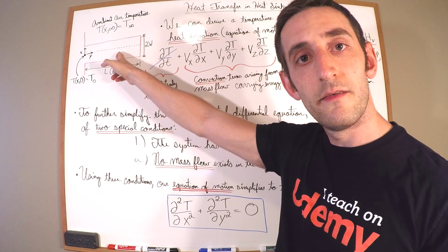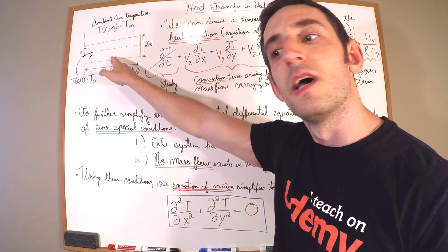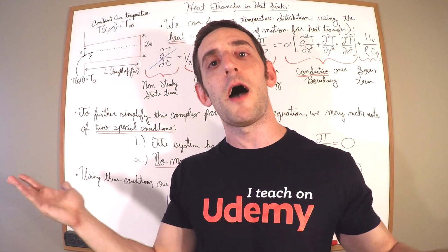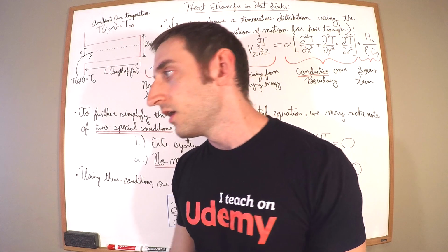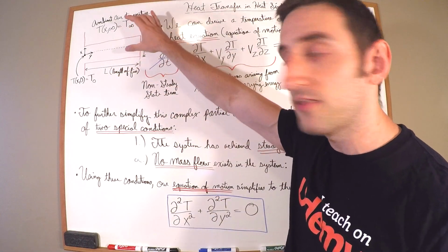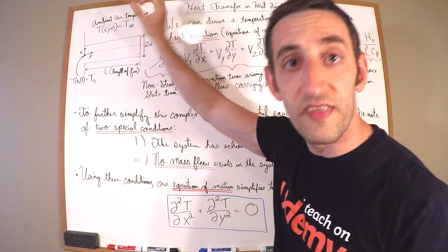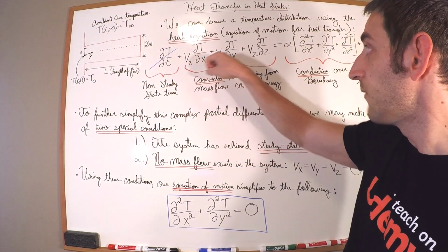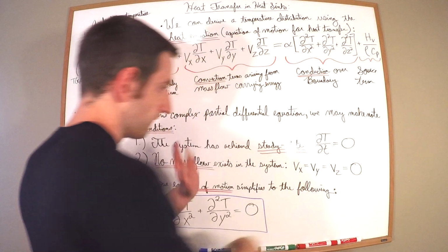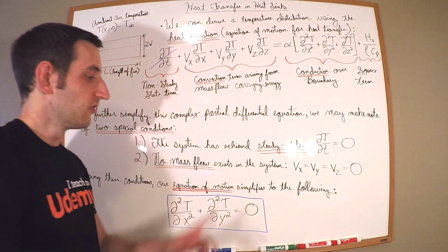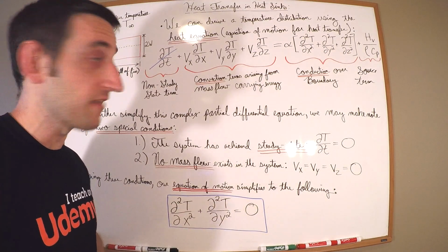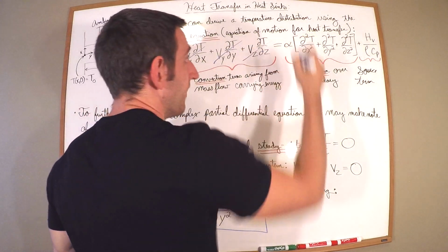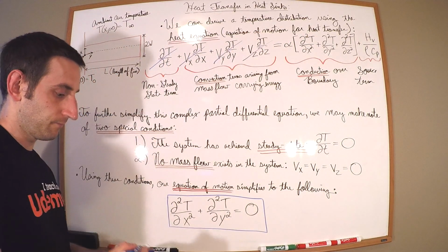This is a solid metal. It's a solid material. So unless it gets super, super hot that it melts, which is not going to happen because then you have other problems, your computer is toast. This guy is solid. It's not going to melt. There is no mass flow within the metal, within the fin. Okay? The velocity of the material, Vx, Vy, Vz, is 0. So that drastically simplifies our equations because we can say that's 0, that's 0, that's 0. We get a 0 over here.